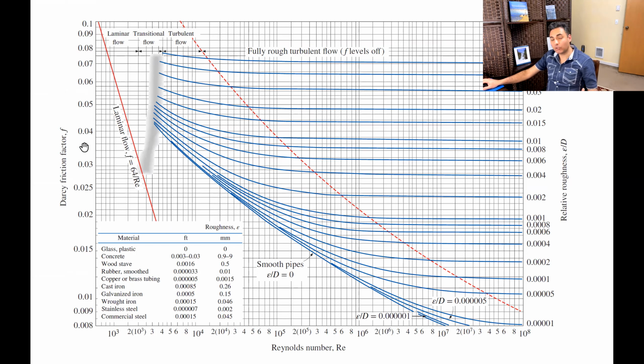And if you have solved a lot of turbulent flow, fluid mechanics problems for this range of diameter, intuitively as an engineer, the number that we're talking about is probably between 0.01 to 0.04. It's not going to be anything bigger than that, or maybe 0.05. That I've never seen 0.05, to be honest with you. But for commercial steel, probably between 0.01 to 0.03 max or 0.04 max.